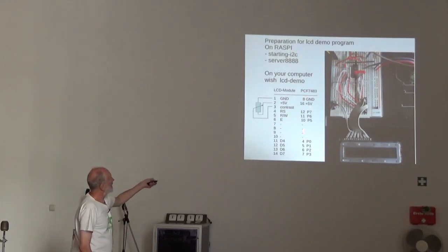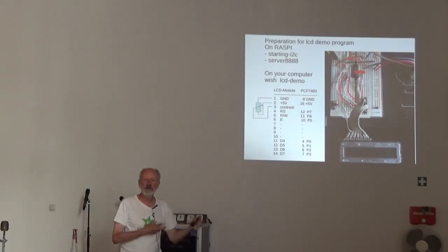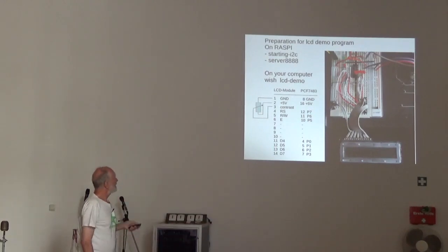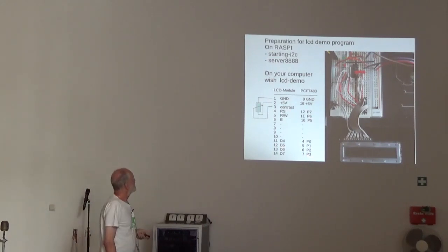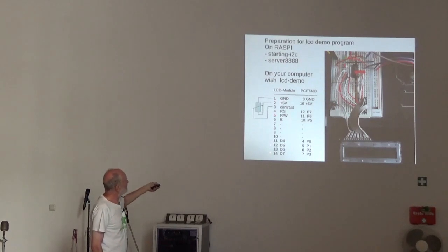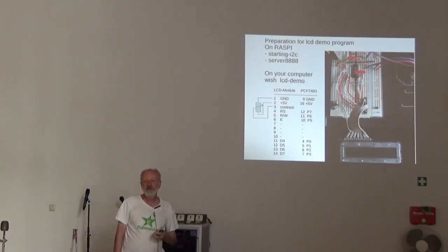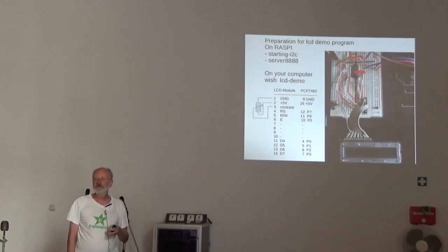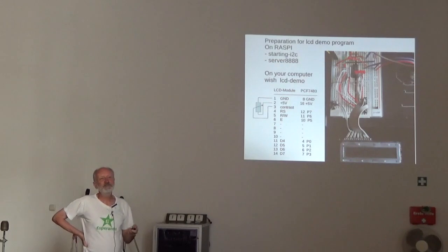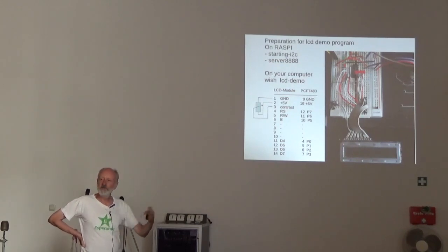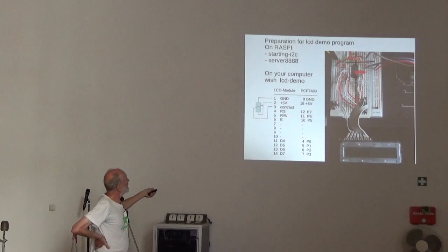The I/O bus expander has 8 pins for communication with other chips again, and I use pins 0 to 3 and 5 to 7. And the LCD module has 14 pins normally, because the LCD chip normally communicates with an 8-bit bus, but we can switch the LCD chip to 4-bit communication, and then we have 3 handshake lines.